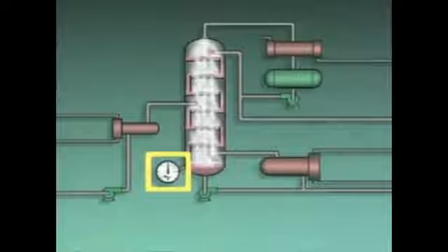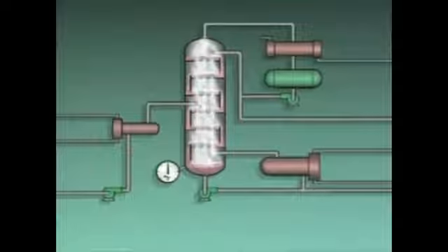By lowering the temperature at the bottom of the column to its proper value, the overfractionation problem can be eliminated, and the column can return to its original operating conditions. In this topic, we focused on reboiler-related problems, and we described an efficiency problem called overfractionation. Now let's try some practice questions.